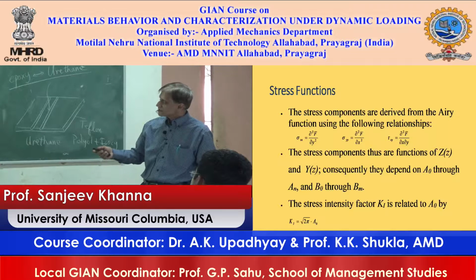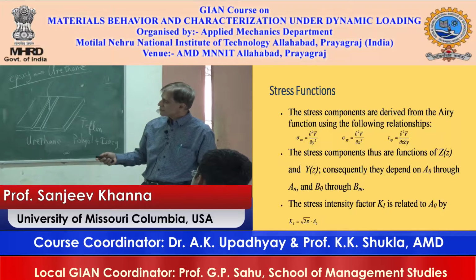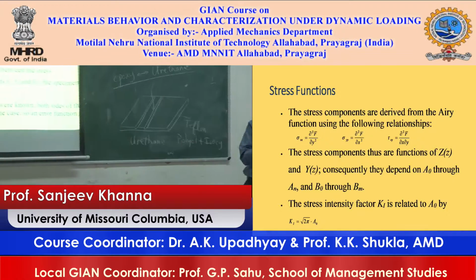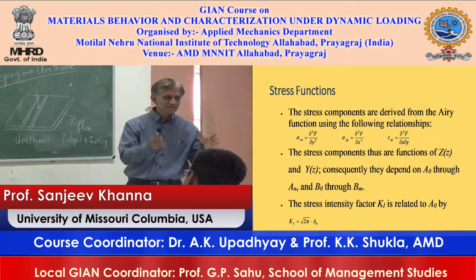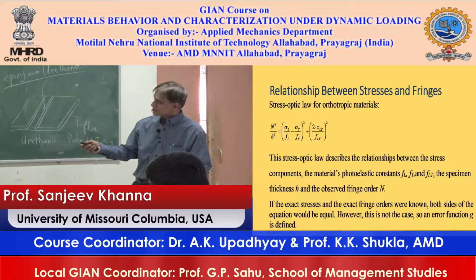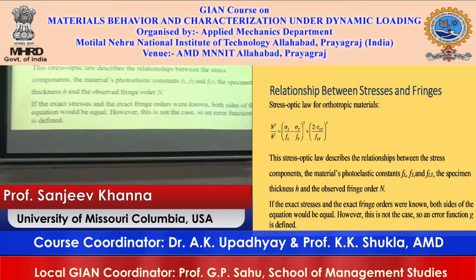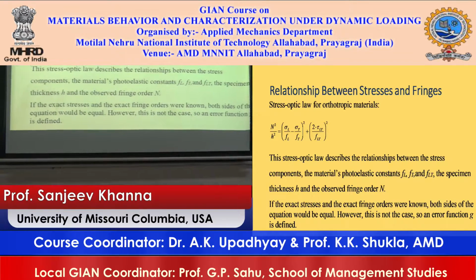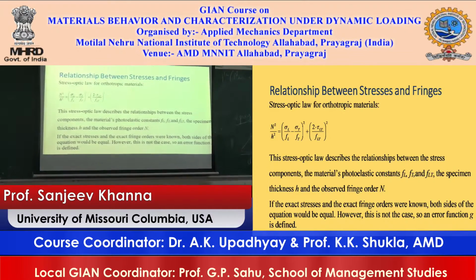This is the state of stress. This is the final stress field. Stress is here, and then I still have not combined it with the optical part, which is the photoelastic part. Okay, so I just have the stress field in the composite around the crack. This is called the stress optic law. Okay, the stress optic law says that this is the order of the fringe n. So I'm showing you those fringes. So zero order is where there is zero stress around the crack in some region around the tip. Then you keep going up, first order, second order, third order.